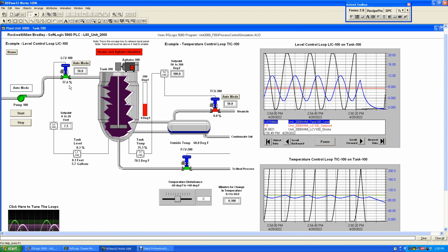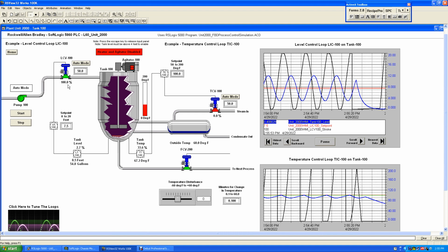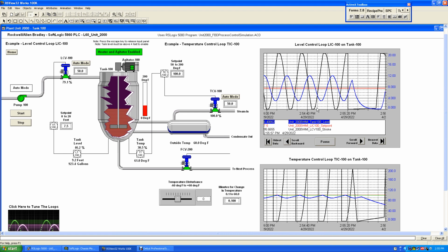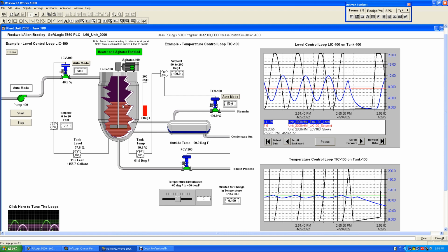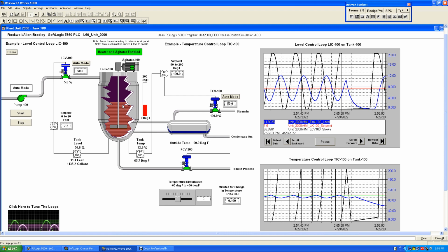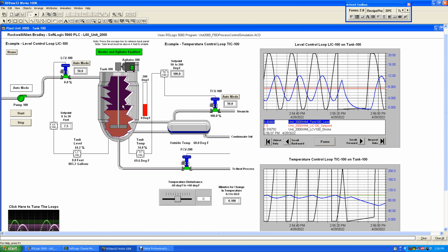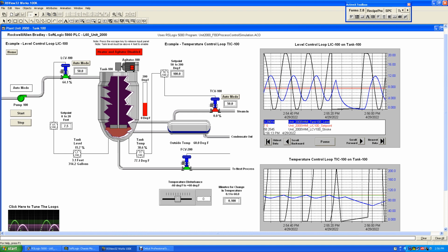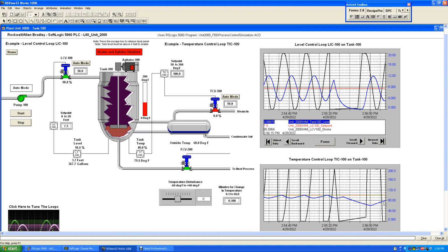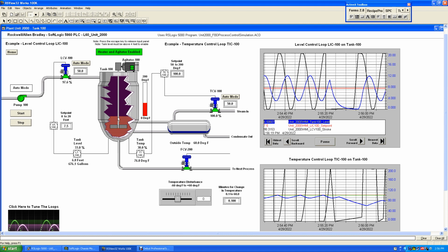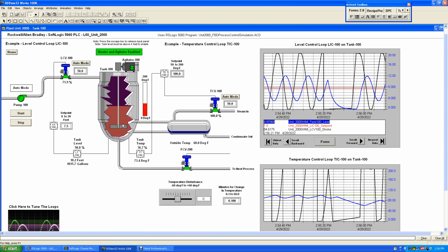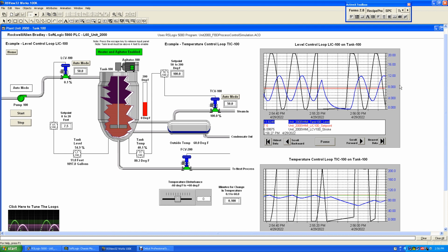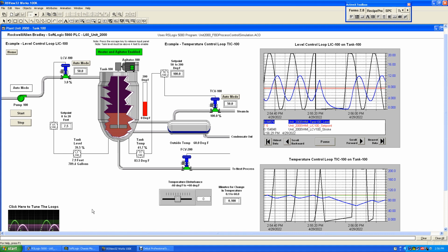You'll see it go green, and you'll see the valve position here opening up to 100%, and you'll see it going up, and then it'll start oscillating back and forth because it's poorly tuned. And then you'll see the temperature come off and on, off and on. As it goes up over 40%, I believe I made it 40%, it could have been 20%. It looks like more than 20% actually. I'll have to go back and look at it. But it starts oscillating back and forth.